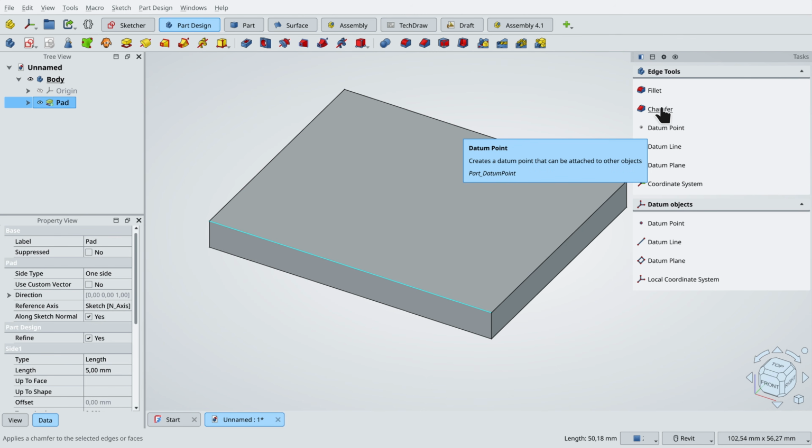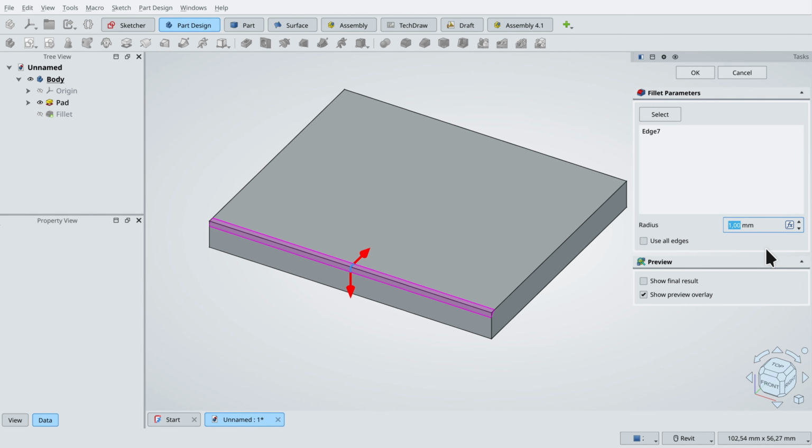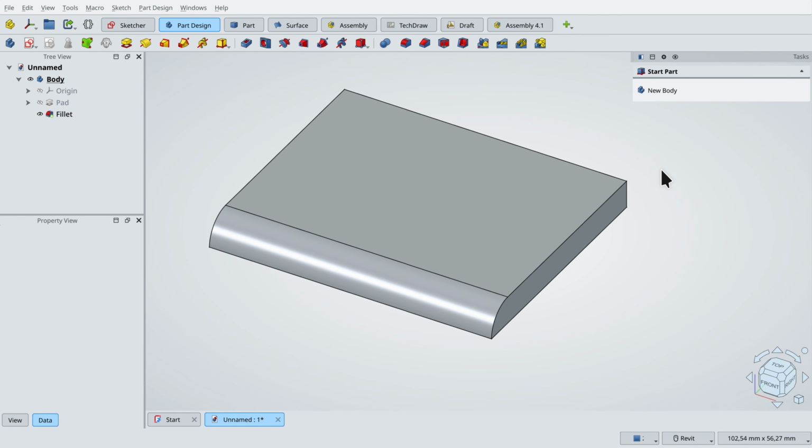Another critical point, you cannot create a fillet that is larger than the available thickness. For example, if I have a 5mm plate, I can't apply a 5mm fillet or anything larger. The software will just give up. If you really need that fillet to cover the entire thickness, you have to trick the software. Enter a value like 4.99mm instead of 5. Keep this in mind because in other CAD software, these limits are often handled automatically, but here you need to be smarter than the solver.